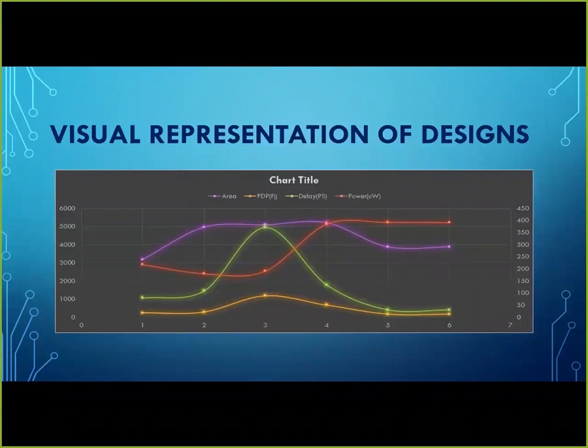So this is the design, like we have 6 designs. The design 1 has 79 picosecond delay, which is the first design which we have, because the Python script which is given to us has 100 picosecond which fails. Then after editing that we got 79. For the second one we got 133. Third one is the ABC. I don't know why, after running that from the ABC tool we got infinite delay. And from the fourth one we got something around 133, and the fifth and the sixth are 30 picoseconds, which we got after the minimization and the optimization of the design. So 30 is the best design delay which we got.